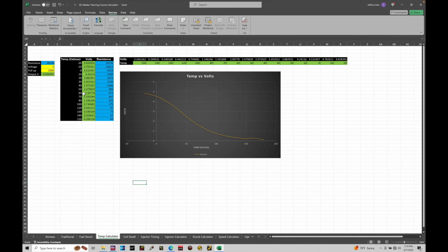Okay, so I just got done hand fitting all of the data from our data sheet into our chart right here. What we're left with is a voltage scale to enter into our calibration table, and then a temperature scale associated to that new voltage scale. So we've translated the data from the sheet to our 1K pull-up ohm on our actual internal circuit, so we're accounting for that. We've entered in the resistance and the temperature, accounting for the pull-up resistance. Now we have a corrected voltage to temperature scaling that we can enter in. So this calculator helps a lot. Let me demonstrate the next step here.